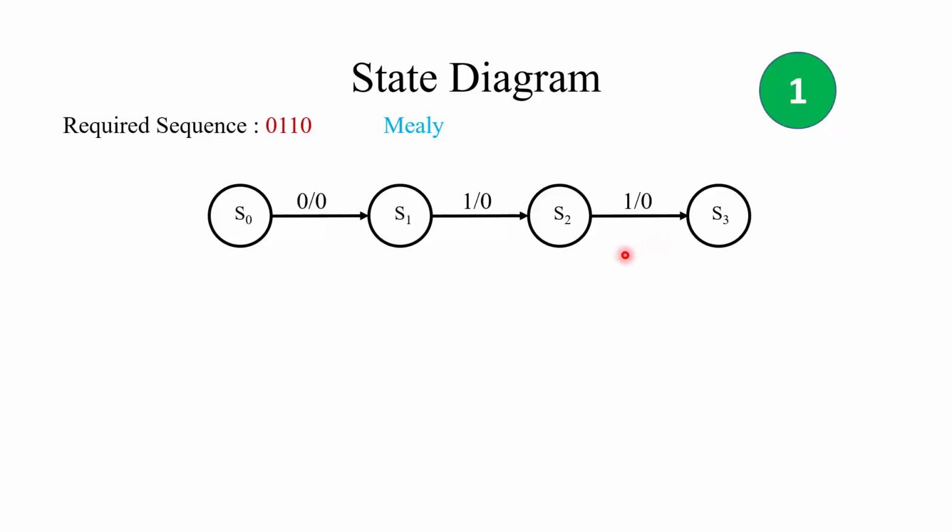After that, we turn our attention to individual states and see what happens otherwise, if inputs other than the required sequence arrive. In case of the initial state S0, it's pretty simple: we will stay on the initial reset state and keep our output low if the input is high.